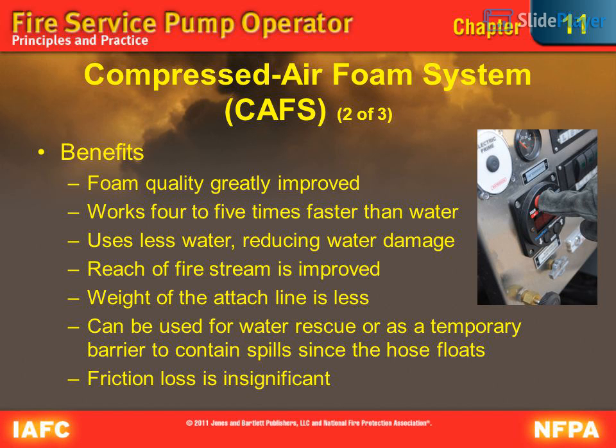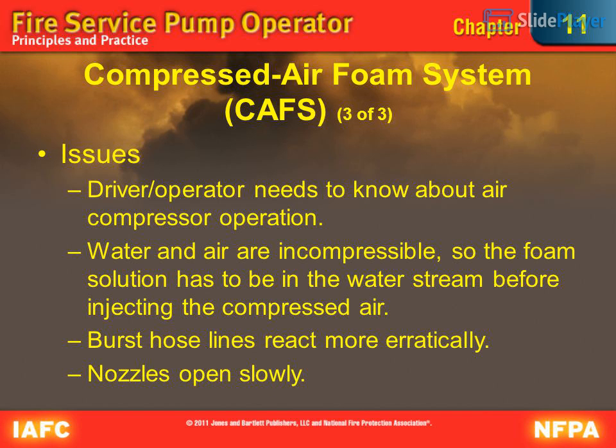Compressed air foam system, CAFS, 2 of 3. Benefits. Foam quality greatly improved. Works 4 to 5 times faster than water. Uses less water, reducing water damage. Reach of fire stream is improved. Weight of the attack line is less. Can be used for water rescue or as a temporary barrier to contain spills since the hose floats. Friction loss is insignificant.